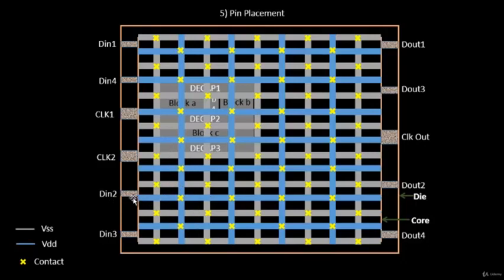Okay, and for example, there are again some cells which will be placed over here, which refers to D in 2, and as a result, D in 2 is placed over here. So there are multiple reasons. Also, we know that we have blocks placed over here: block A, block B, and block C. So no cells and no flip-flops can be placed in this area. We have made sure that all the input ports, which are D in 1, D in 4, D in 2, and D in 3, are out of this particular area.